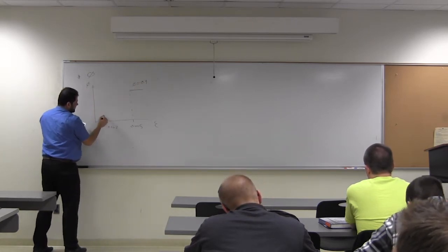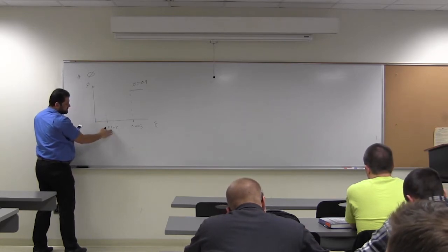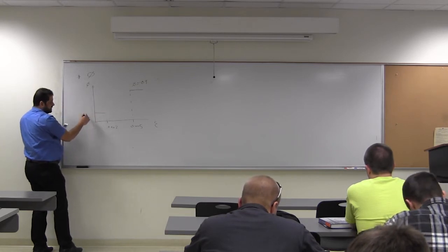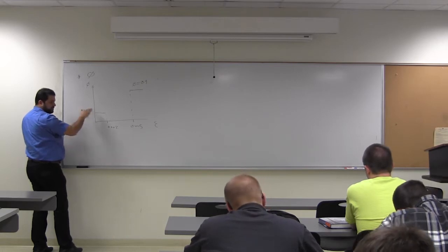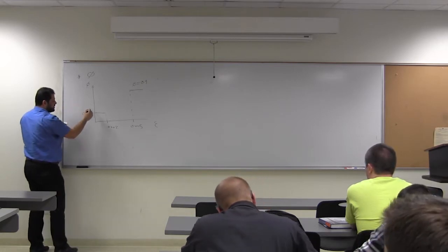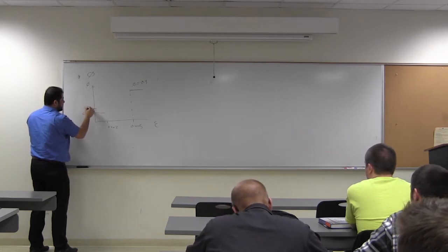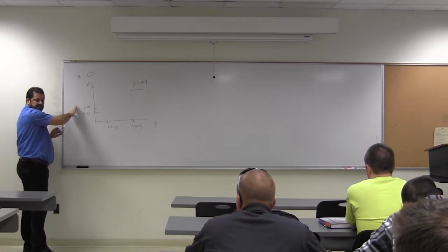Then we said if the strain in the steel at ultimate is less than 0.002, the Phi factor also becomes constant, and it's equal to 0.65 for members with ties, or 0.75 for members with spiral confinement to the main steel.